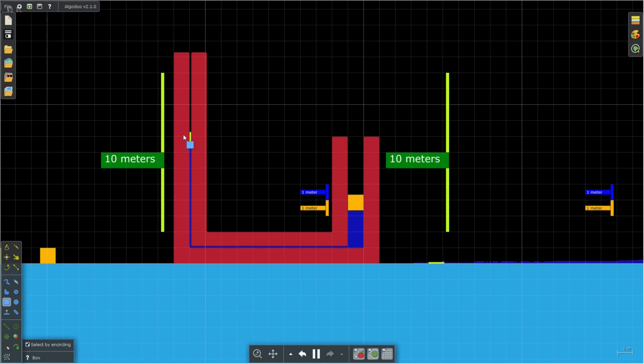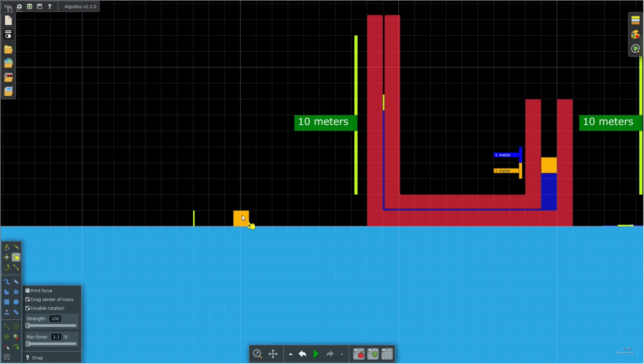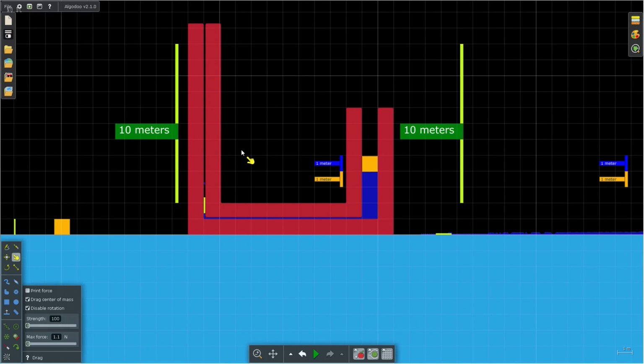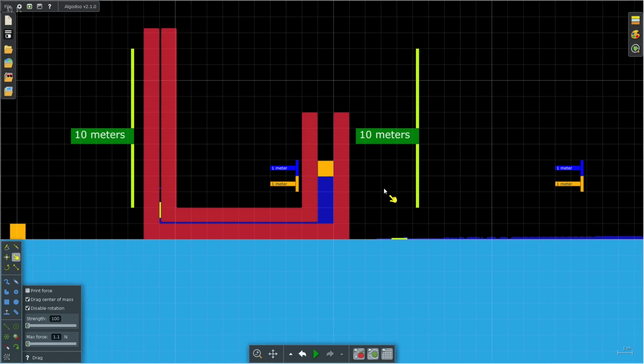You can tell that moving this with the same amount of force somehow multiplied it when we moved the orange block. Because again, when we went back here, we're not able to move this freely. It's stuck. And yet, when we move this downwards, the orange block on the right moves. So, that's just to say that force multiplies when you're moving something like this because the areas are different, and that's related to Pascal's principle.